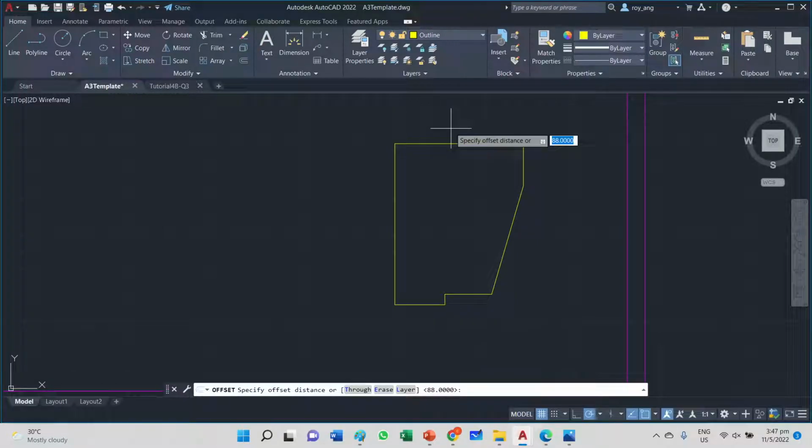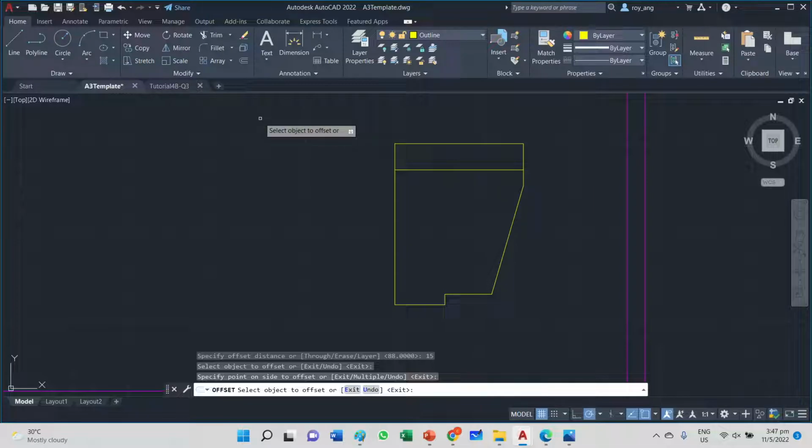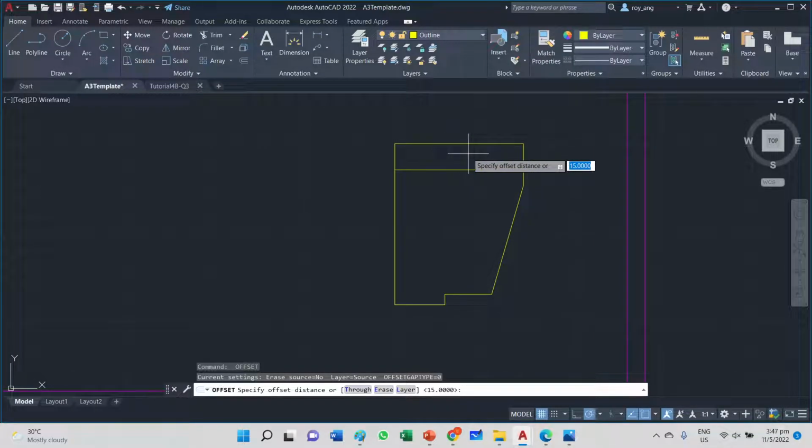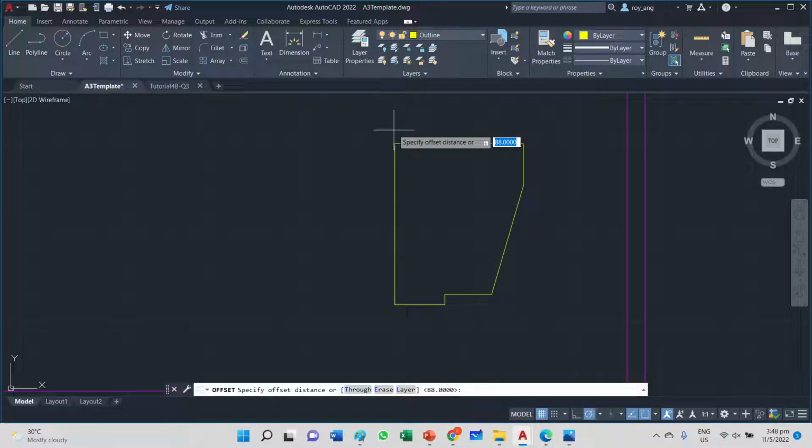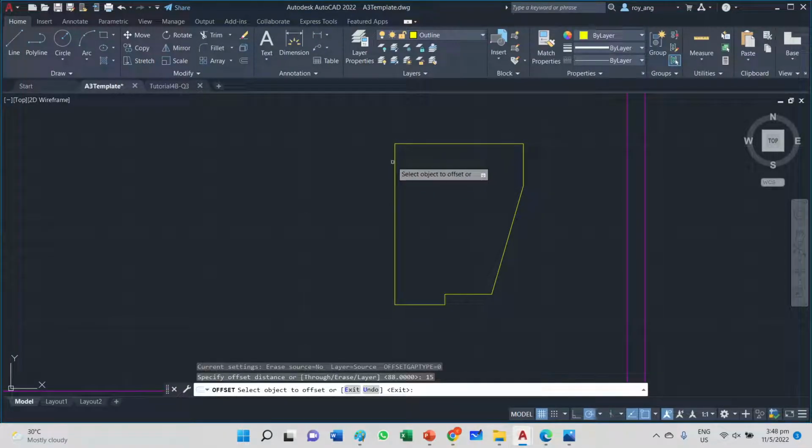The next thing I'll go into is the hidden line. And that's one way of doing it. The hidden line I want to address first is the hidden lines that's coming from the hexagonal feature. I'll start off from the base, drawing all the way to the back, and then I'll shoot up to the full height. Okay. And then I will offset by 15. Draw this portion all the way down.